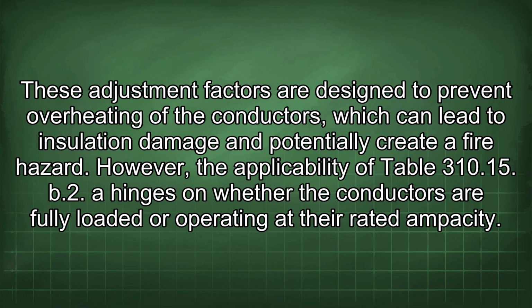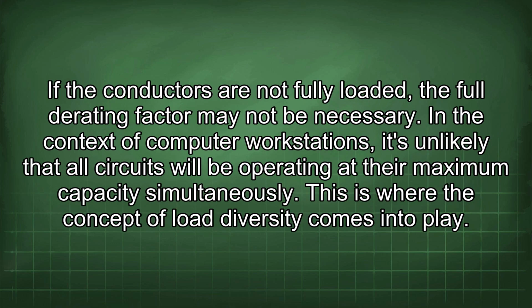a fire hazard. However, the applicability of Table 310.15 B2 hinges on whether the conductors are fully loaded or operating at their rated ampacity. If the conductors are not fully loaded, the full derating factor may not be necessary. In the context of computer workstations, it's unlikely that all circuits will be operating at their maximum capacity simultaneously. This is where the concept of load diversity comes into play.